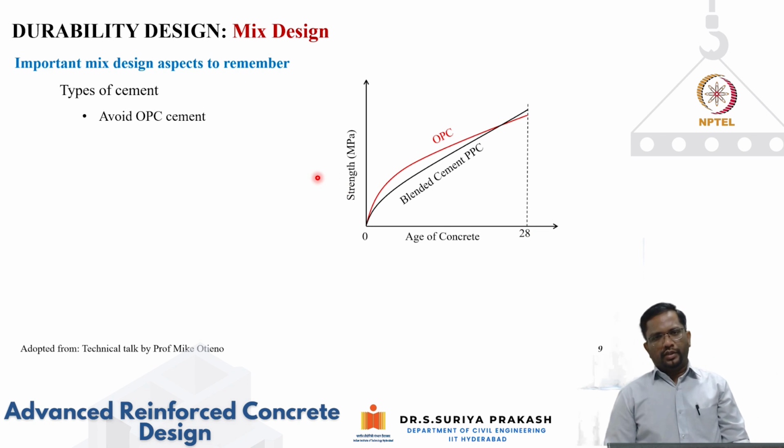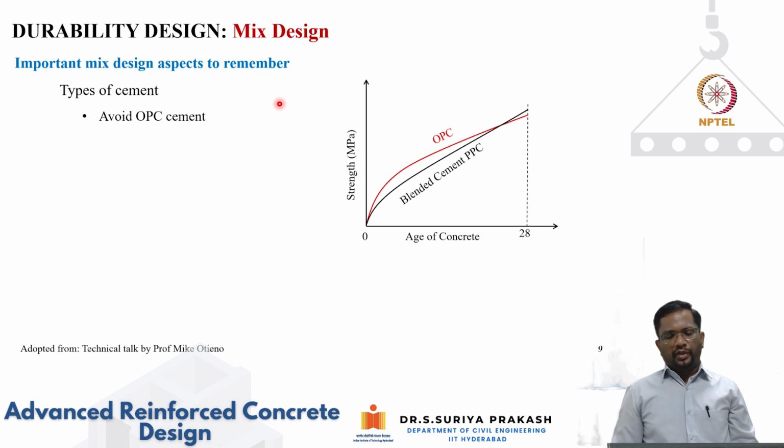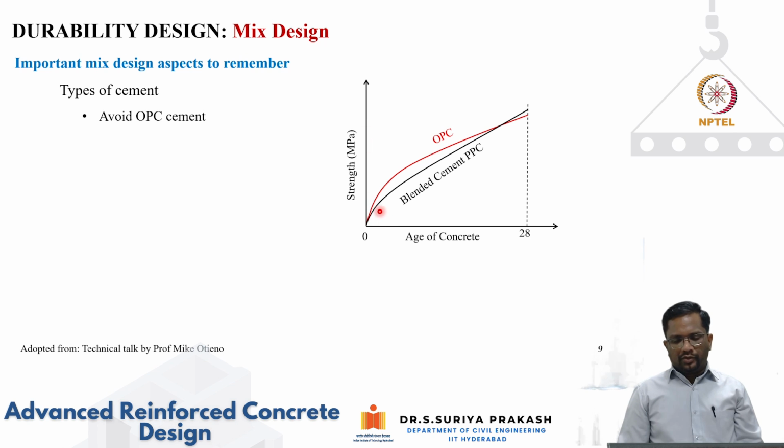Right, now mix design. I think we have talked about this in detail. It's very important to consider the mix design aspects. We have seen that for tackling most of the deterioration mechanisms, using supplementary cementitious materials is going to really help. So it's better to avoid OPC cement and go for a blended cement. And you can see that with the blended cement, though your initial strength gain may be slightly slower than your OPC based cement, if you look at the age of 28 days after casting, you can see that